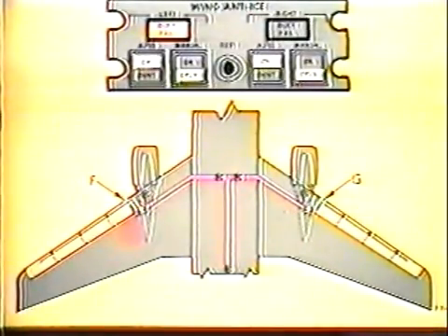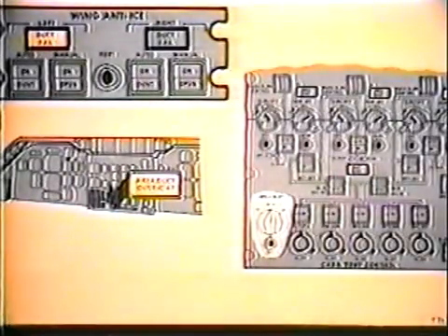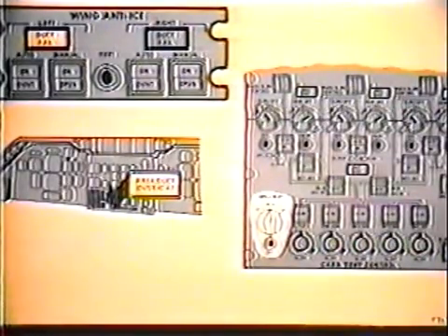The duct fail lights will illuminate to indicate that the temperature in the area around the outside of the wing anti-ice ducting is excessive. A probable cause is a leaking duct. These lights are a part of the area overheat system and are designated as areas F and G. When a duct fail light illuminates, the area overheat test button and selector switch on the second officer's air conditioning panel are used to determine whether or not the light was illuminated by both overheat detector loops or by one loop only. The area duct overheat light on the pilot's annunciator panel will also illuminate.